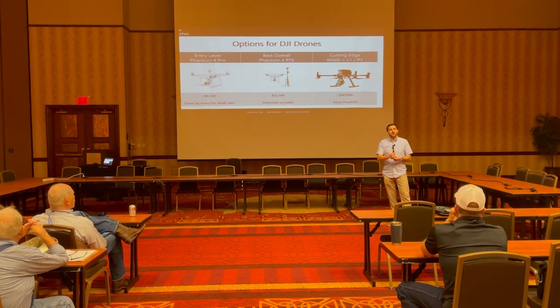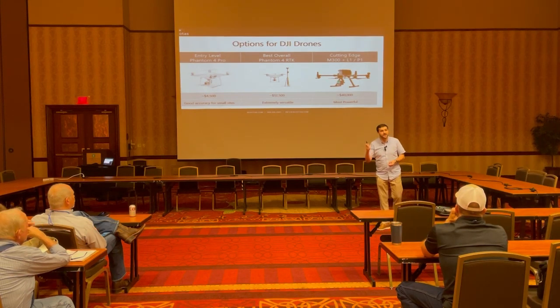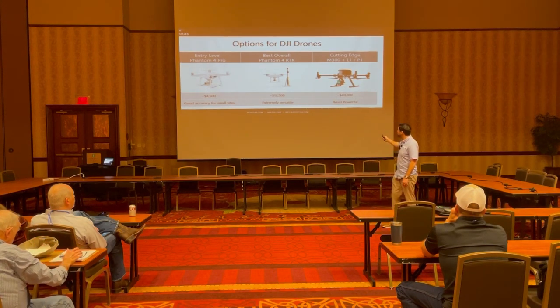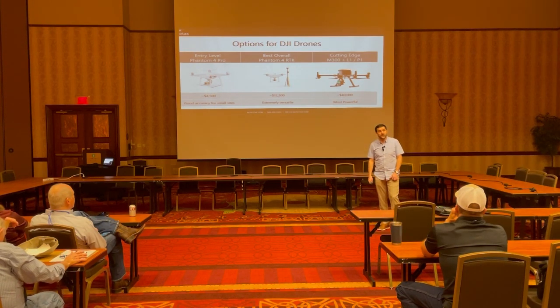Biggest thing, I'll give you the cliff notes there. If you're working primarily in non-vegetated areas, so if you're doing parking lots, strip malls, or roadway corridors without a huge amount of vegetated areas, a Mavic 3E with photogrammetry is probably going to be your best bet.